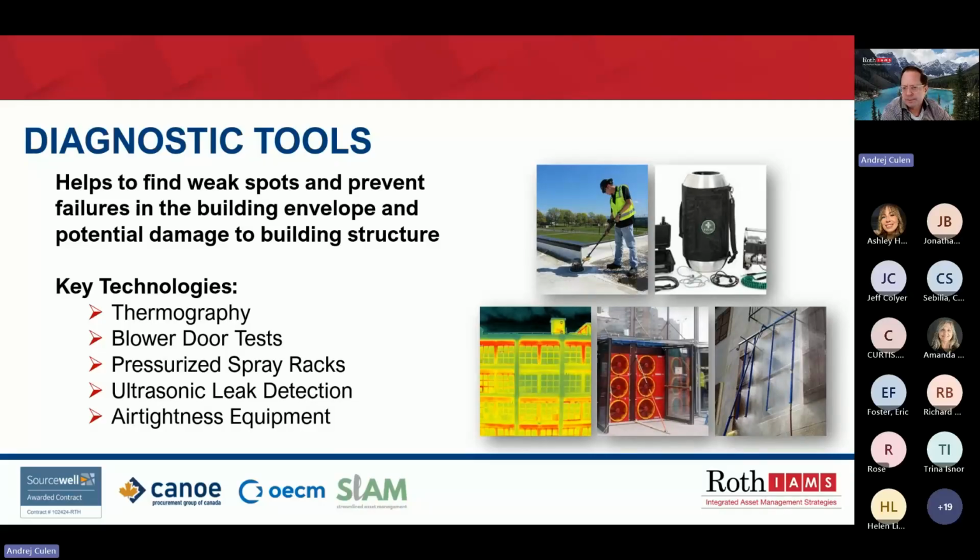What they are used for: air leakage, identifying and sealing gaps that allow uncontrolled airflow; water intrusion, finding vulnerabilities in the building's exterior where water can penetrate; thermal performance, evaluating insulation and identifying areas of heat loss or thermal bridges to improve energy efficiency; and quality assurance, verifying that the building's construction meets design specs and industry standards.